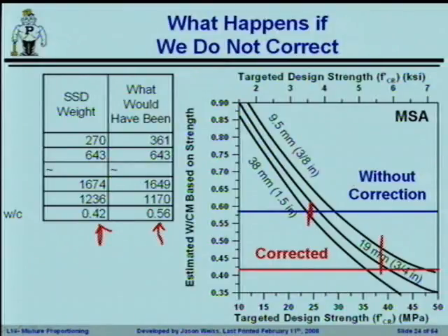And this is really why the slump test came into being when they were doing these lightweight aggregate ships. They were wanting to control the moisture in the lightweight aggregate. I mean, in these cases, we're talking about, those numbers were in the order of, I think it was 0.7% and 0.5%. Is that what the absorption capacities were? When we talk about a lightweight aggregate, the lightweight aggregates you're using, Ryan, are about 10.5%. So those are huge numbers that we would need to be adjusting for if we don't get it right.